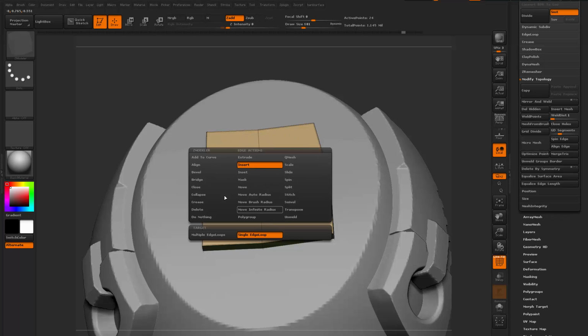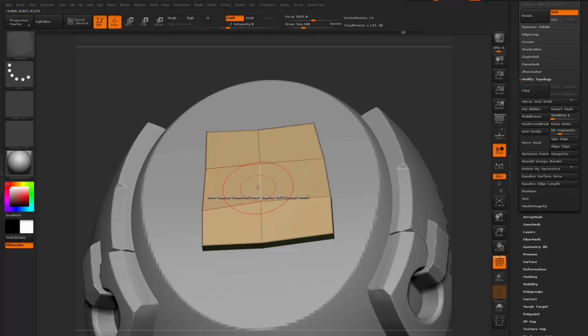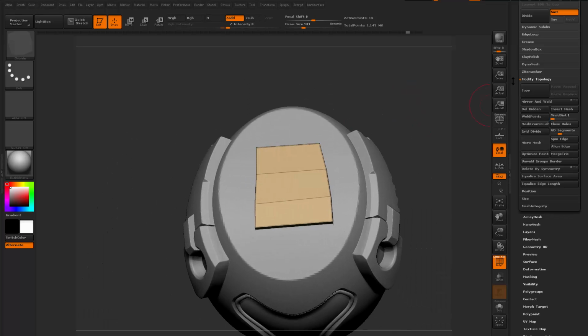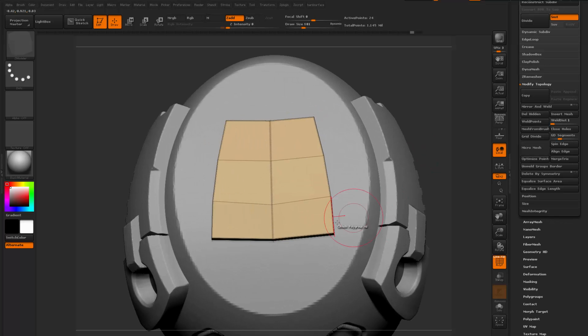That's going to change my command into an auto command that can be applied to an edge, and there is a delete. The target will be an entire edge loop to delete that, and then I can do the mirror and weld. It's going to give me something better.